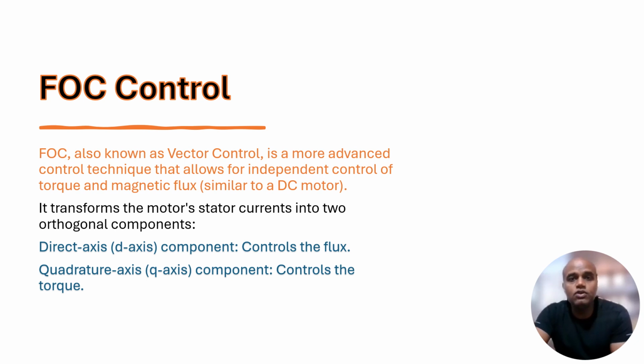So the concept of the direct axis and the quadrature axis are part of a mathematical transformation used to simplify and control the motor operation, especially in the FOC. They are aligned with the motor rotating magnetic field and are used to decompose the motor magnetic field and current components for easier analysis and control.